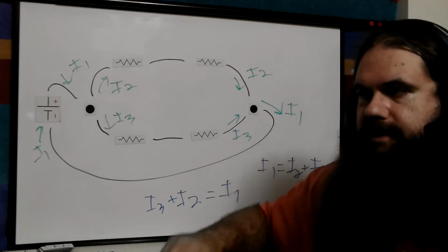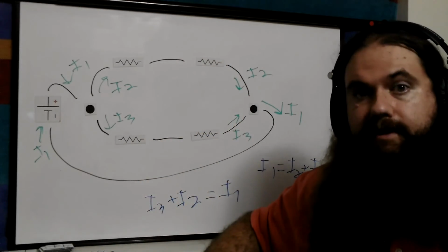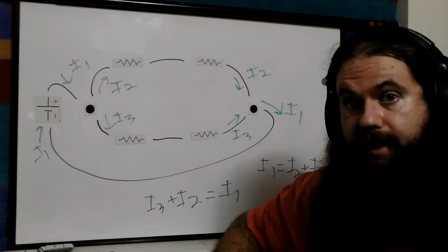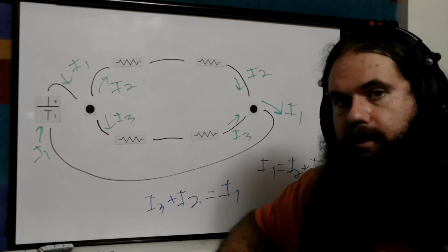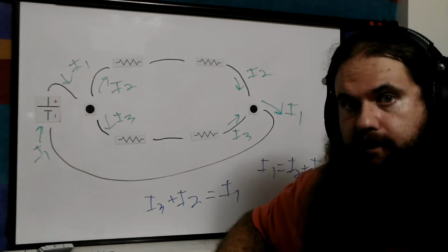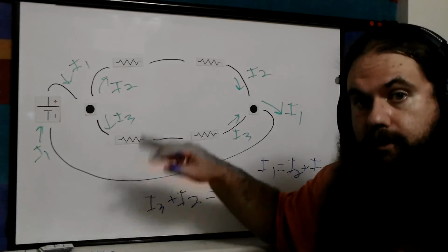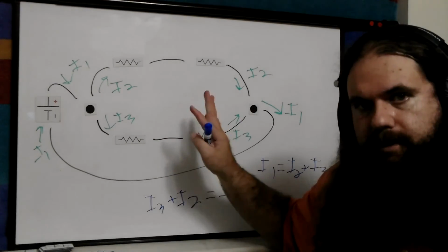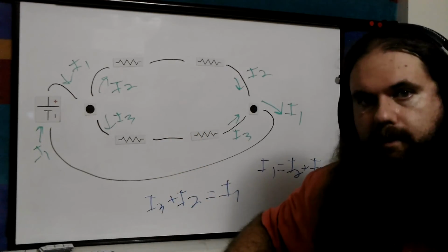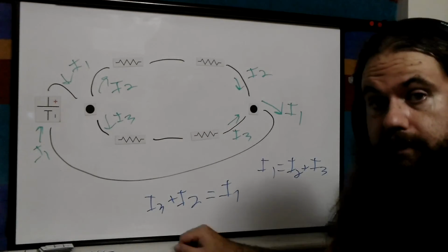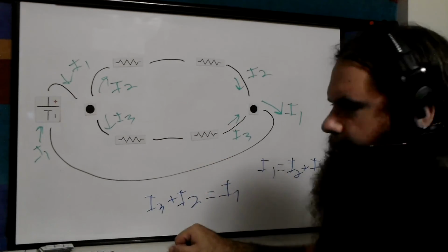The voltage law just says any loop, you have a net zero voltage. You have your power, then you have your drops of things happening equal zero. Your current law just says you have as much going in as you have coming out. It's almost like the conservation laws. So it took a while to show the math, but that was just showing you how it works. Using it is very simple. Add them up equals zero. And remember, if you get negative currents, just flip the arrows. And now you have everything you need to know to work with and maintain simple circuits.